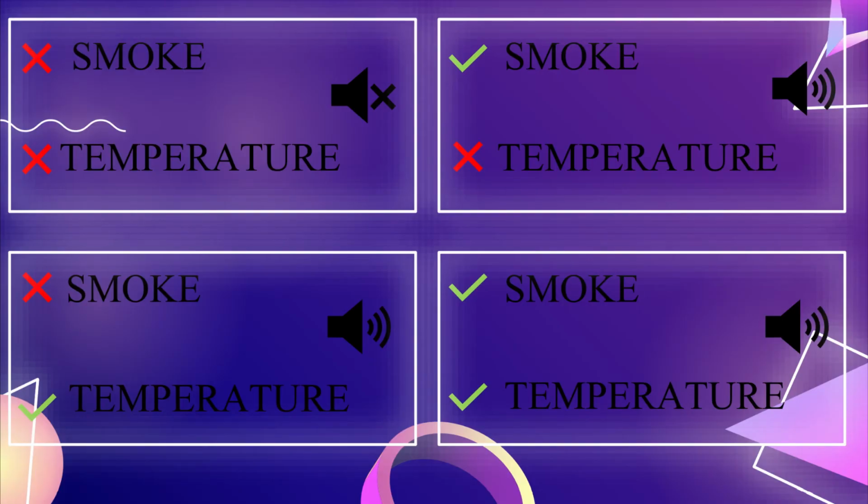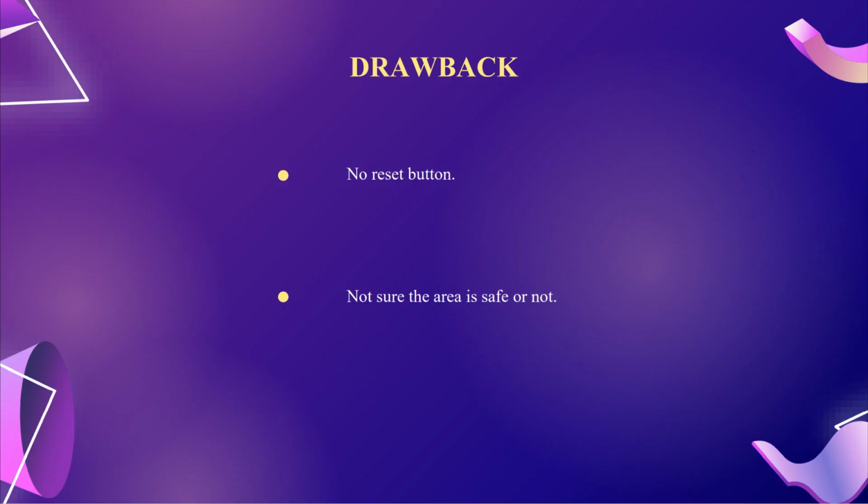Using Tinkercad as a medium for running the simulation for the system, the result shows that the system works as intended. The system was able to independently detect and trigger when there is either heat, smoke, or both. One of the drawbacks of the system that has been noticed in hindsight is that the system would revert once there is no presence of heat or smoke. An improvement of the system would be to have a switch to reset the alarm. The switch must be manually triggered by a person to ensure the safety of the premises.